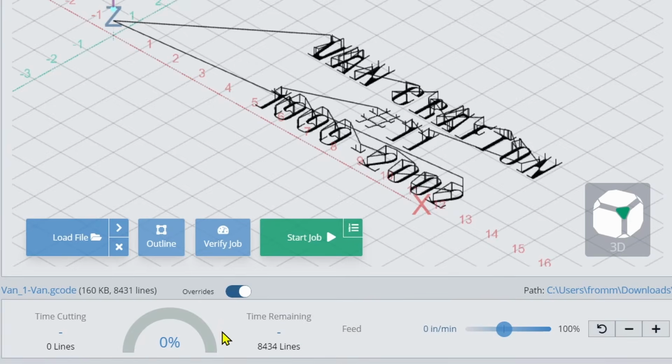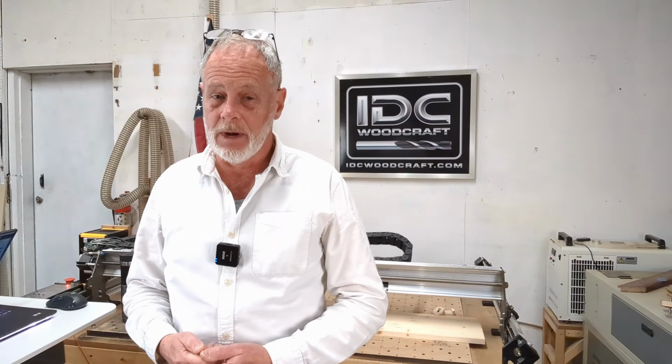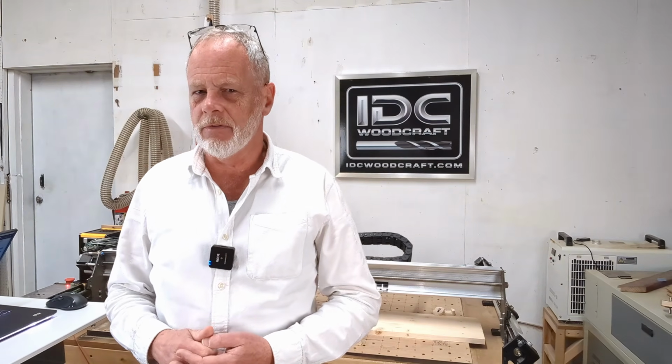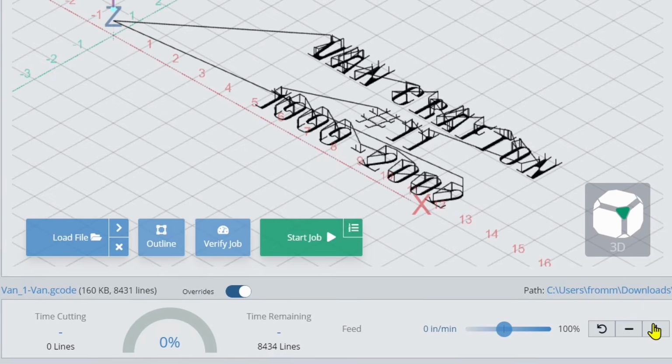And what this is going to display is, number one, this little speedometer looking thing is going to tell you the percent of this thing left, and there's also going to say time remaining. So it's a good little visual indicator. This little slider here changes the default feed rate of your router bits that are set in the machine. So if your router bit is set to 100 inches per minute, then you can change that on the fly by simply moving that slider around. And then you can also incrementally change it with the plus and minus buttons right here, and you can reset it to the default 100%.